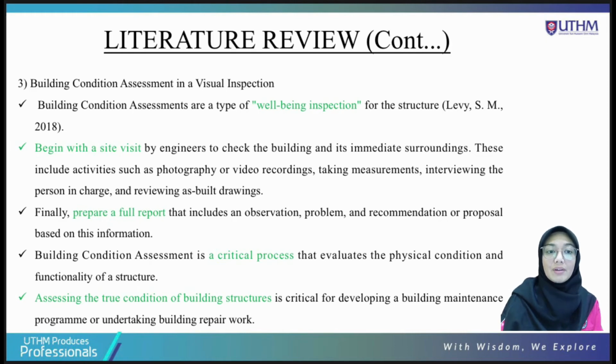So, begin with a site visit by engineers to check the buildings and their immediate surroundings. This includes activities such as photography or video recordings, taking measurements, interviewing the person in charge, and reviewing as-built drawings. Finally, prepare a full report that includes observations, problems, and recommendations or proposals based on this information.